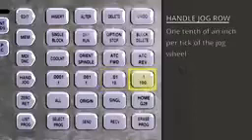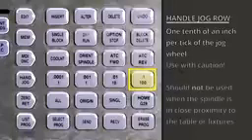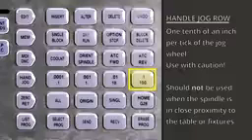And finally, the fourth jog key over represents the tenths jog key. For each tick of the jog wheel, the machine will move 0.1 inches. This jog increment must be used with caution as the machine moves very quickly, and it's easy for the operator's input to exceed the machine's ability to quickly respond, resulting in a bit of further motion even after the operator stops turning the hand wheel.